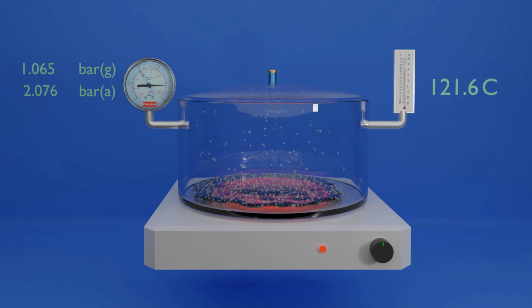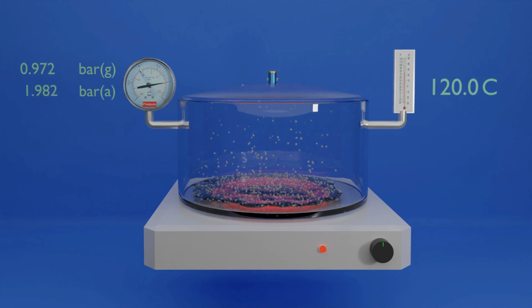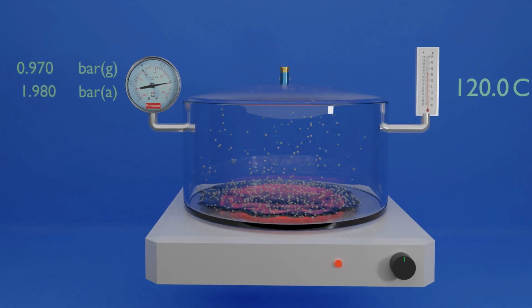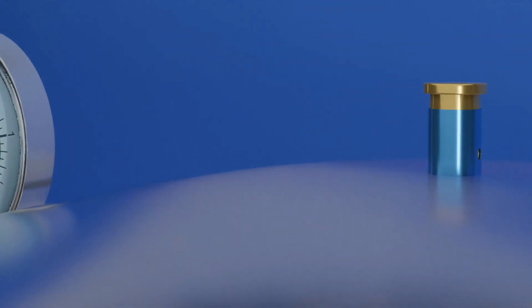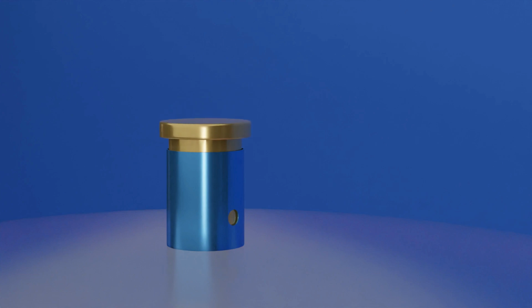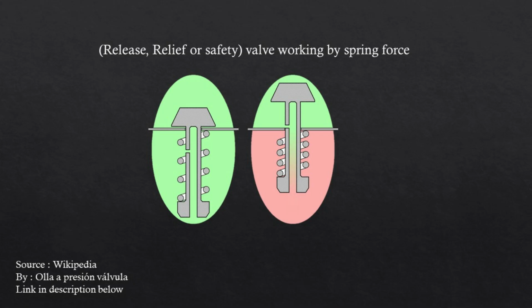The pressure cooker usually operates at 120 degrees Celsius, which is equivalent to 1.98 bars of absolute pressure or 0.97 bar of gauge pressure. In this experiment we see that whenever the pressure rises above a relative value of 0.97 bar, this pressure value will cause the valve to lift, allowing steam to leak out and the pressure to drop again. The steam valve has several shapes, but we chose the simplest shape for clarification, and in general all valves work in this same way.